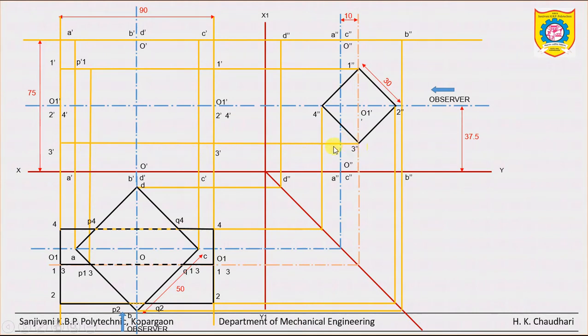So just identify the horizontal projection from edge number 3 and locate that point. Similarly, first we have taken this side of projection, so here will be Q dash 1. So P dash 1 and Q dash 1 are on the top edge. Similarly, here will be P dash 3 and here Q dash 3. Now we have got 4 points.